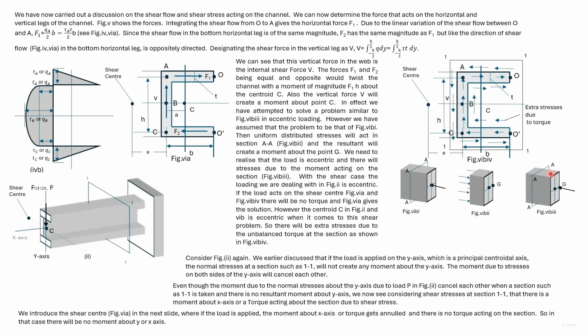For this problem, we'll get the stress at AA by using the formula P divided by area and adding the stress due to the moment.